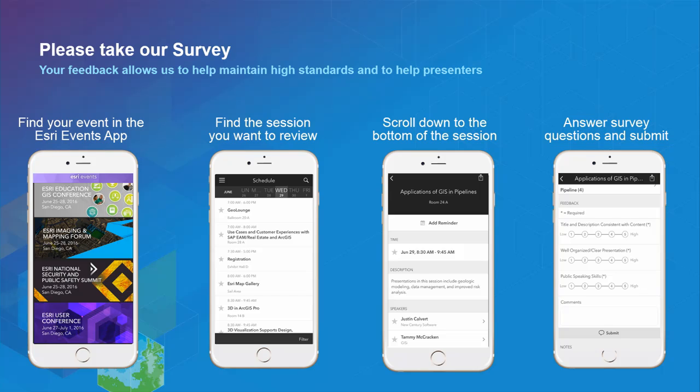This is a very good question, and I hate to tell you this, but the answer is no, not right now. We don't have a way to do that. You would have to go into Python and write a Python script that would update that specifically. The Python arcpy.mp module works very well with map series. You can access all the pages and make adjustments as you're exporting. One of the things you can do is put a text element on and update that to say whatever you want through a Python script. I think that's the only way to do what you're trying to do right now. It is a very good requirement, though.